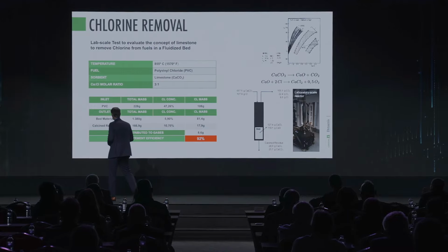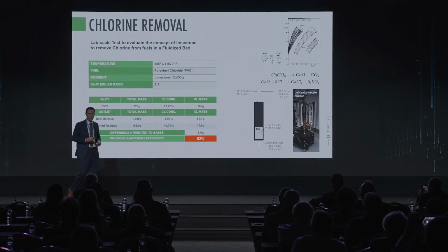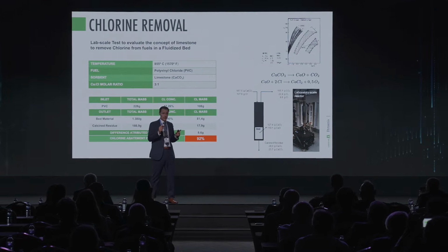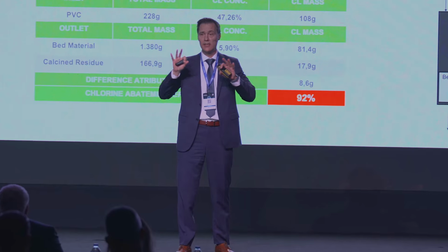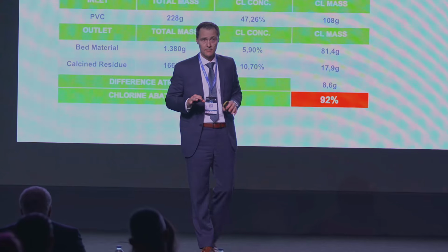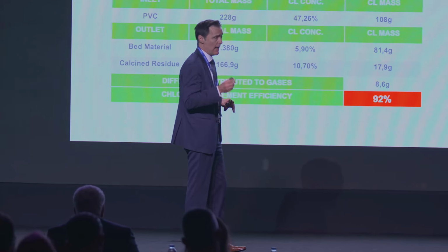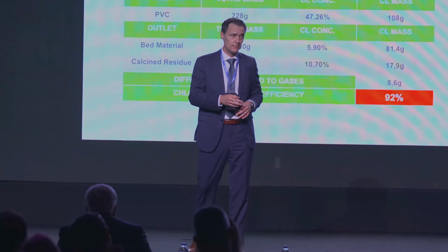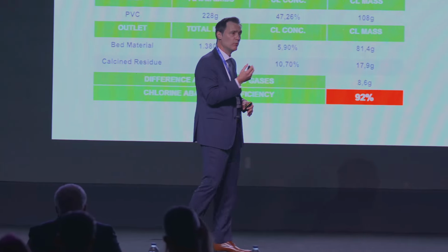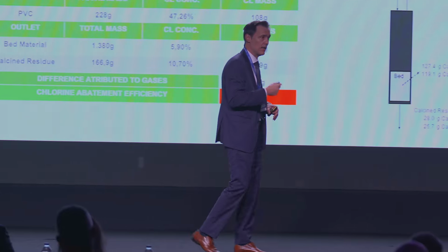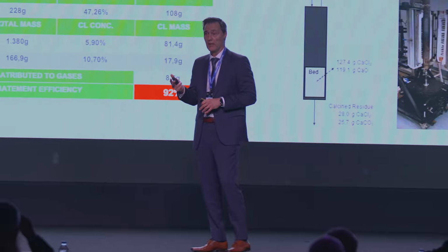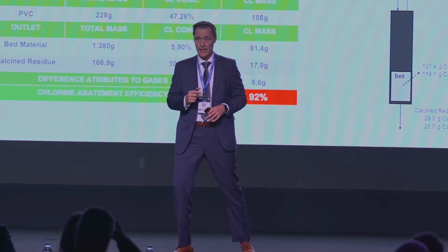And finally, another important feature of this equipment is related to the gas cleaning. Since the gasifier is separate from the process, we can add sorbents like limestone to the bed and remove the acids like chlorine, sulfur, and fluorine. We can clean the syngas.